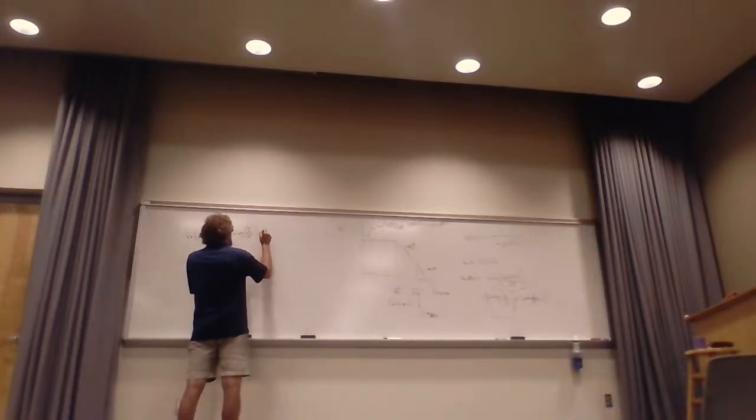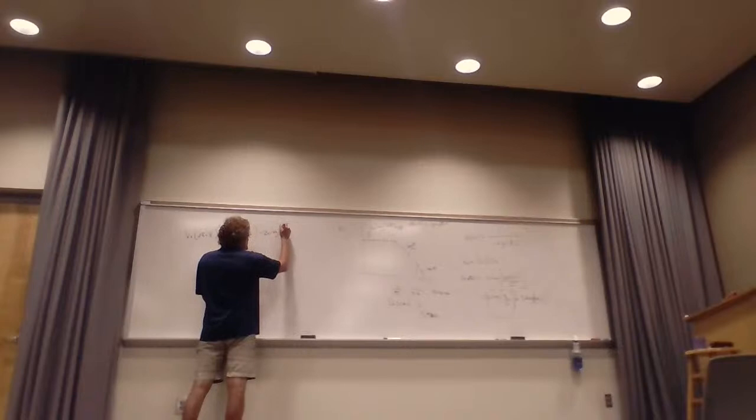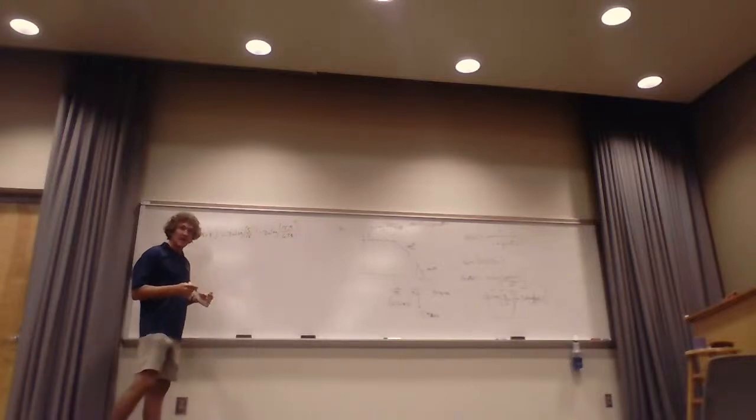So we take minus, because it's falling, this 20 dB per decade times the log. Now we take the ratio of the upper frequency, which is 15.9 megahertz, over the lower, which was 6.36 megahertz, right? I get rid of the meg. I just leave that on. Correct, class?